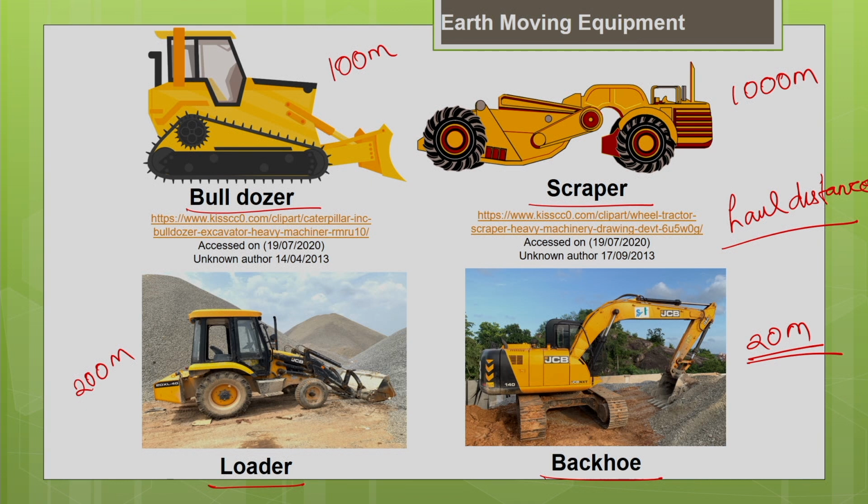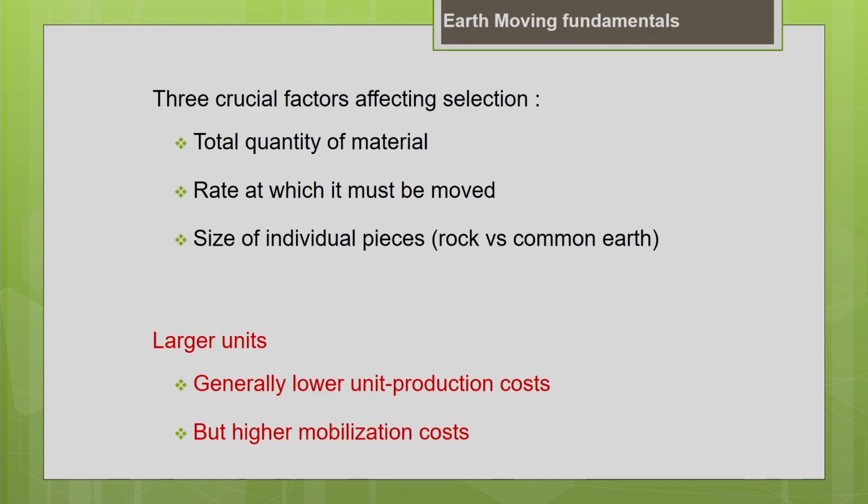Another important thing is your project requirement. So, basically what are the project requirements? You need to know the quantity of material to be excavated, so that I can know it from your contract specifications and the drawings. Okay, so I can get to know the total quantity of material which is to be excavated and how much duration is allocated for this particular activity.